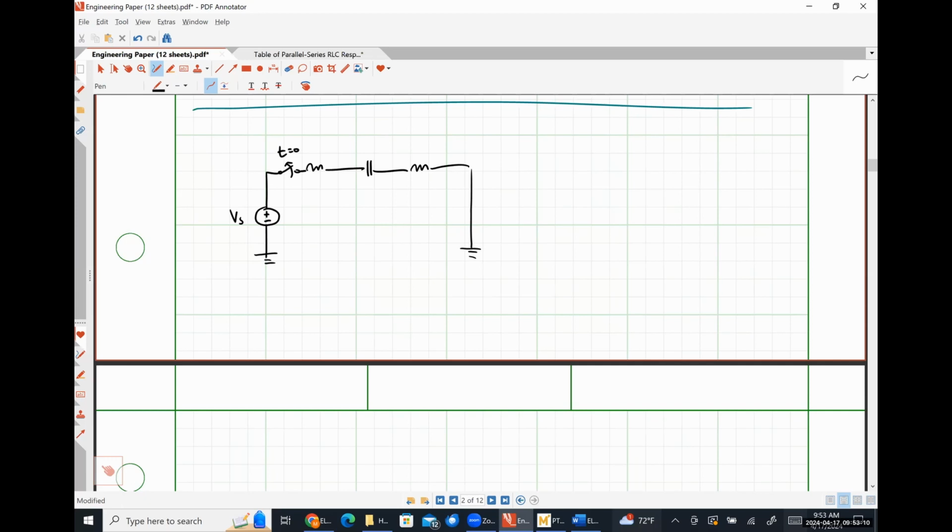So like 2 to 2.5 volts or whatever. One thing you have to watch out for with those is because they're so large, they take a very long time to charge up. They also take a very long time to discharge. If you were to disconnect one and you don't allow that energy anywhere else to go, it will stay there. And then when you touch it, it'll shock the hell out of you.